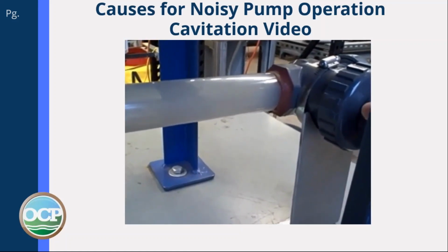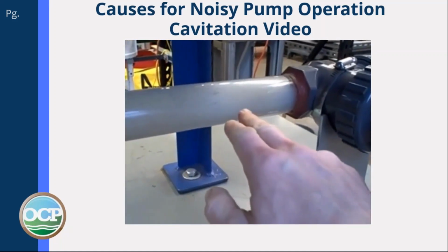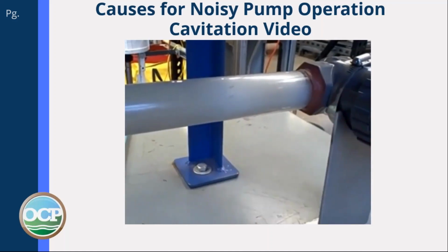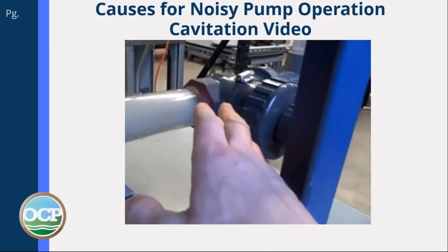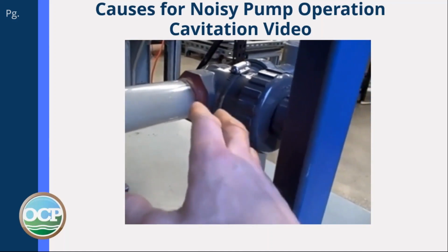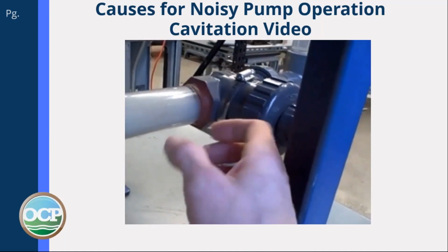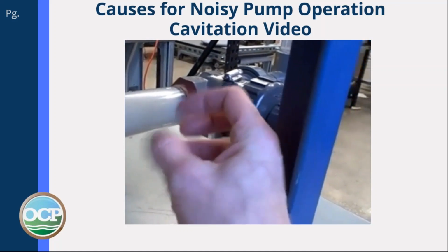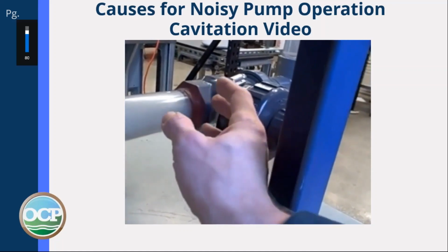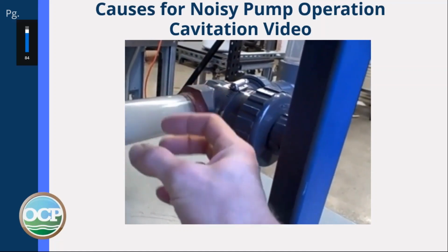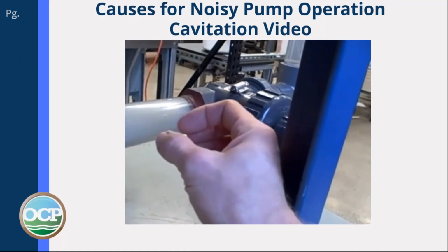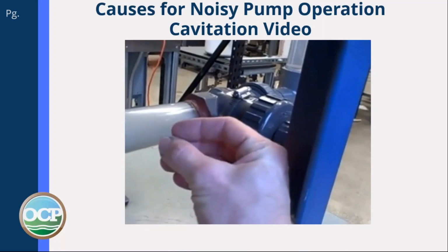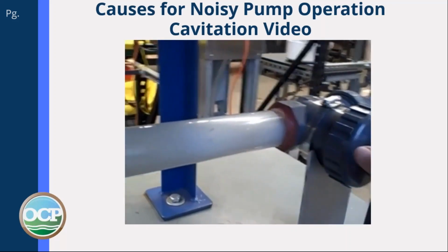You can really hear it now. You can see it occur inside of here. It's a very pronounced action and noise. As the water goes through the valve, it reduces pressure going through the restricted valve. Its pressure drops below the vapor point of the water at this temperature. It flashes into steam, and then after it comes out of the valve and expands again, the pressure goes up, and what happens is those vapor bubbles collapse back into liquid, and that's where you get the cavitation effect.